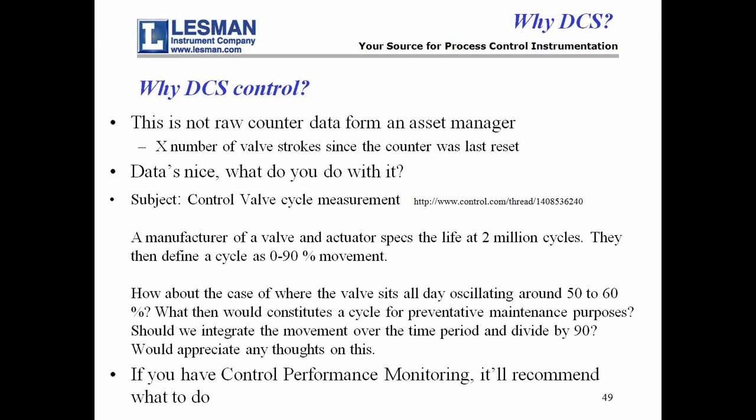I'm impressed by that. You've got to be aware, again, when bringing resources to this, it's sort of like the other stuff where you've got to have some networking skills. And this is at 2 levels, because the platform communications is largely Ethernet network, and also the field bus stuff that you get into with DCSs: Foundation Fieldbus, Profibus, or EtherNet/IP. That is a different skill set than what the ordinary guy that works with 4 to 20 or 0 to 10 volts uses. You can see the guy in the picture down there using an analyzer to try and check out what's going on there.